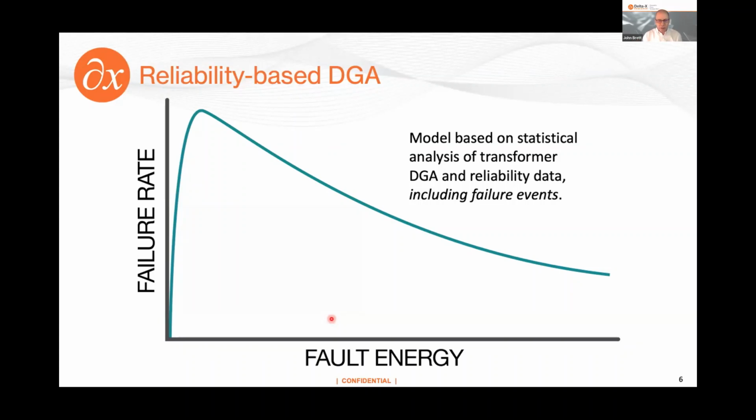Of course, it is difficult to account for gas loss. So if you have a transformer that's leaking gas, not all of it will be accounted for, particularly when you're doing manual sampling, i.e. you have a long period between samples. It's much easier to catch those types of things with online monitoring. Now, what's the important thing in this model? Well, the standards basically imply the more gas you have, the more at risk you are.